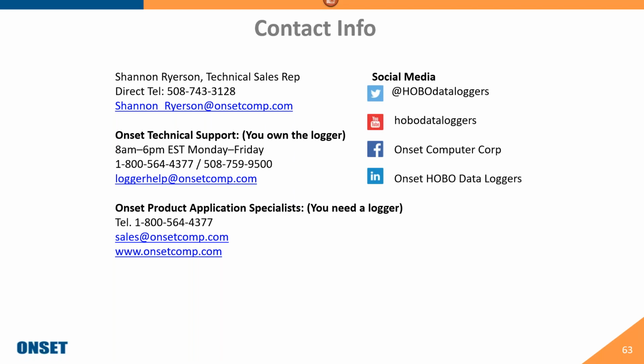In a normal building office setting where you're seeing anywhere between 25 to 65% humidity, it's usually under 1% a year. We do have a NIST certification program, so if you want to send something back in, you can certainly do that to get it recertified.